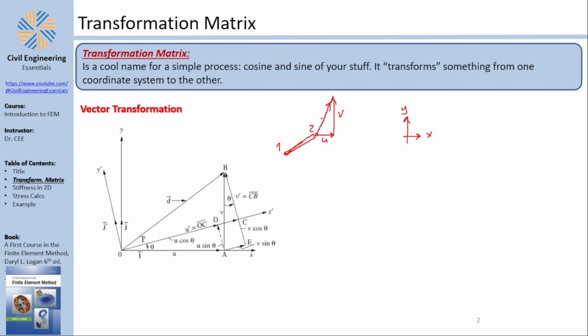which gives you a displacement vector d. Obviously, you know that from the previous lecture, which I will link above on the top right side. We know that the stiffness matrix has to do with something called the local displacements, because the forces in the truss are connected to the extension of the truss, because delta equals PL over AE, which gives you that P equals AE over L multiplied by delta.